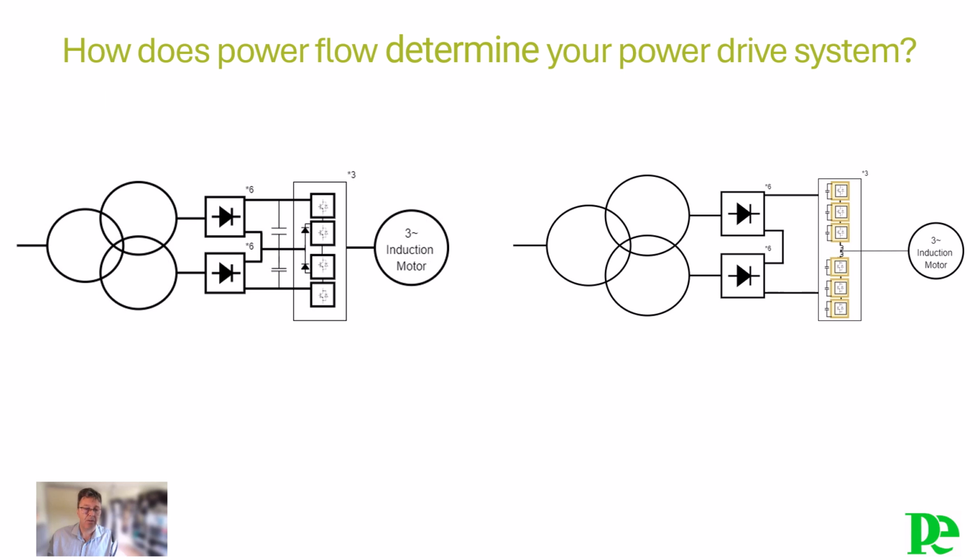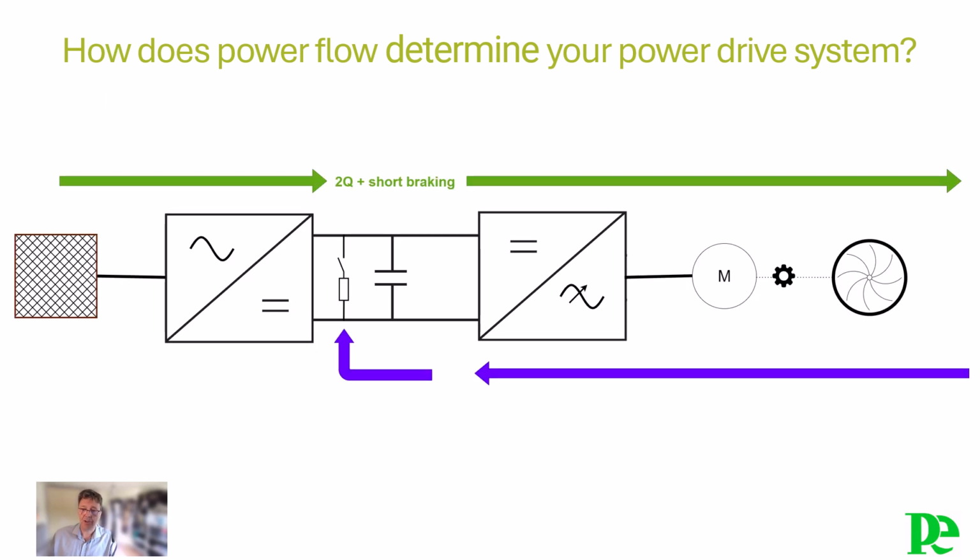When braking the machine, the power flows in the reverse direction, that is from the load to the motor. If the power flow reverses intermittently, an electronic braking unit can dissipate that energy into a braking resistor, enforcing a deceleration ramp to a high inertia machine is a typical use case. Occasional braking energy recovery is in most cases not economically viable.